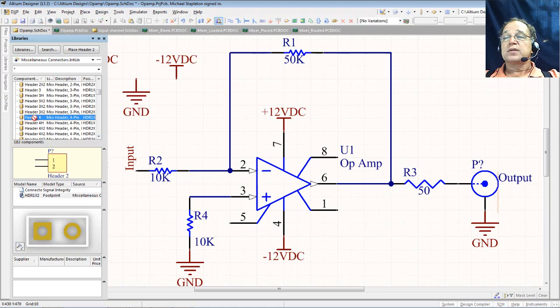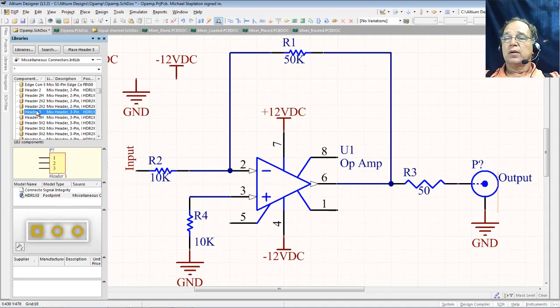They come in different sizes. There's a 4-pin header, 4 holes. You'll notice that when I look at my 2-pin header or a 3-pin header, there's a schematic symbol, there's the 3 holes, there's also a 3H. Now the difference is, and we'll look at this one, here's my 3 connections on my schematic. Here's the 3 holes in the board where I'm going to solder my parts, but you'll see that I have this drawing here.